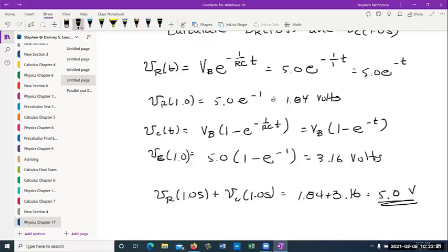So that's one of the test problems. You just plug the numbers into the equation. You're like, oh, that's an easy problem. And it is an easy problem, so don't blow it. And I'll pick R and C. If you pick R to be small and the capacitance to be small, then this thing drops off really quickly. After 1 second, this could be like 0.000 volts, and this could be 4.99999 volts. But I chose this particular case because it gave you a reasonable balance between the two.